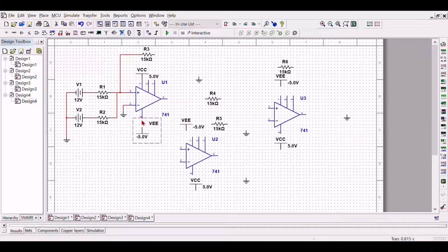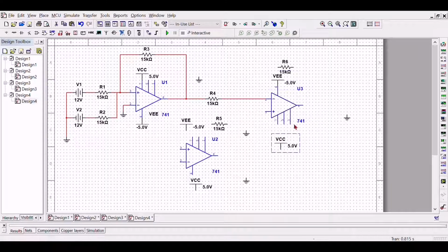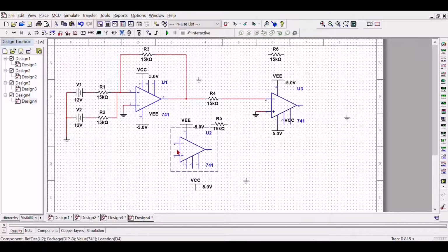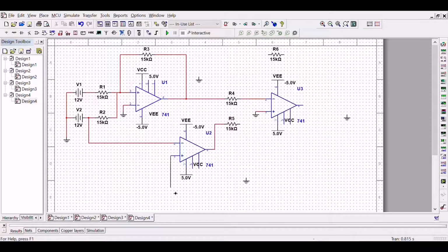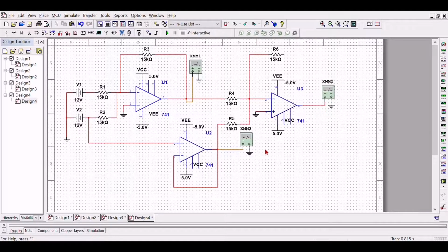The VCC used is 10 volt and the VEE is -10. This circuit consists of V node 1, V node 2, and V output node. For V node 1 I got the value of -4.503 volt, V node 2 is 1.999 volt, and the last one is V output, which is 7.343 volt. All the values are the same as the calculation, so this is proof.